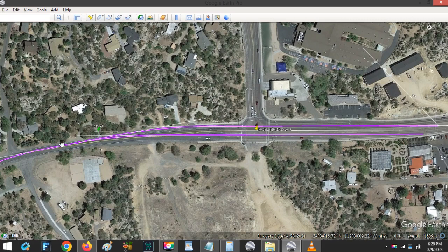If it extends, say, 2,000 feet back, that's about halfway to the low spot. So you could raise the point of vertical intersection some feet in order to compensate for the long vertical curve, whether it's a simple curve or parabolic, I don't know. It's not especially any high speed, so it might as well be a simple curve.